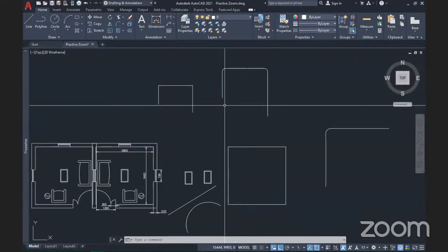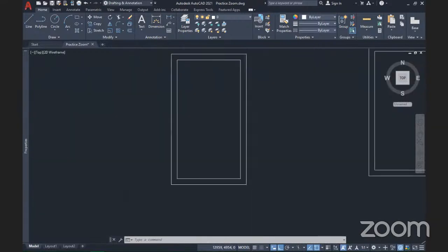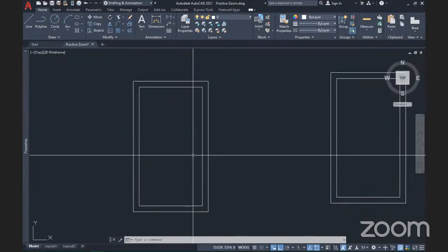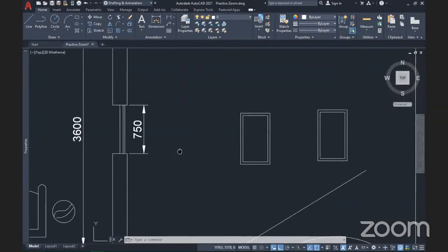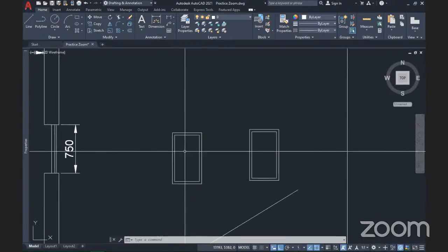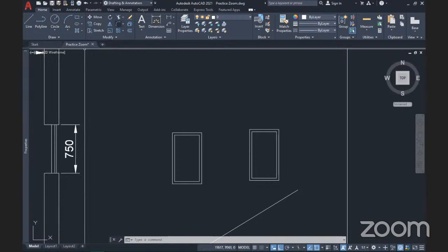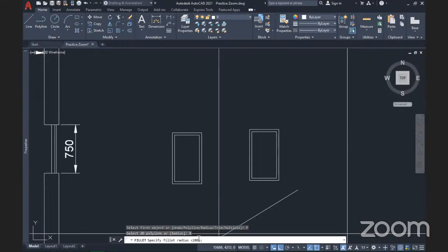So having said that, I will need to effect some changes, first of all, on our test project, and this will be our lab rats. We use it to test with this before we go into the building, so I won't spoil what's inside the building. So now, I'll just need to create a fillet and make a very nice curve around the inner rectangle. So I'll click on the polyline option, and I will change the radius to 70.